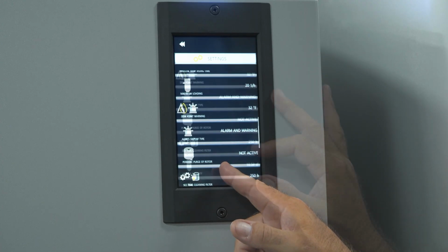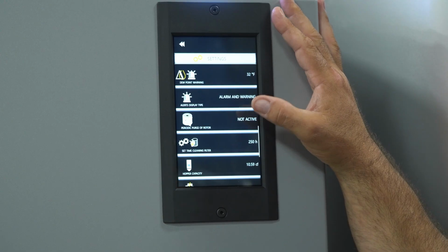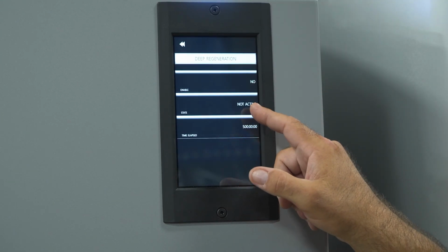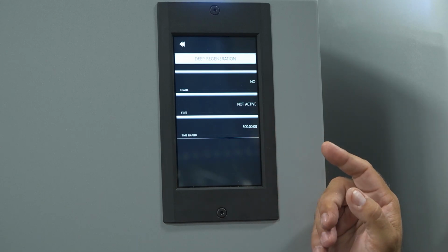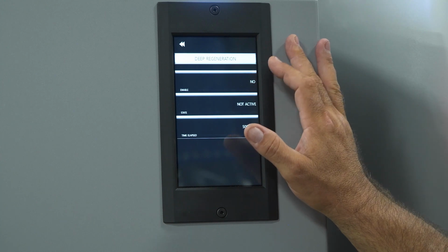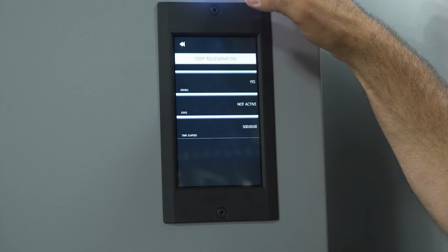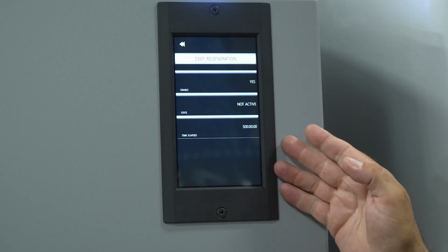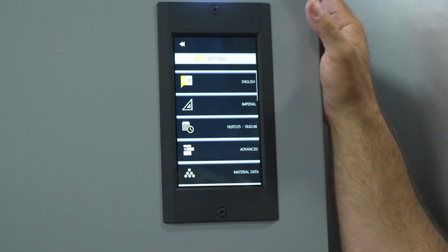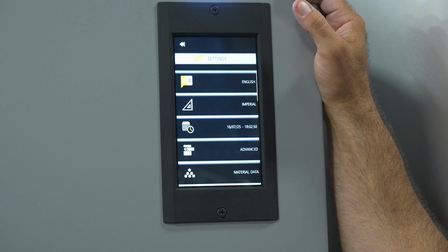And then the next feature is your periodic rotor cleaning. That's something you'll have to decide, but I would enable it. That will clean your rotor and maintain it so you don't have to replace your desiccant wheel as often. So we'll go ahead and enable that. And then it'll periodically clean the desiccant wheel, get any plastic dust or anything that got in there. It'll superheat the wheel to clean it off.